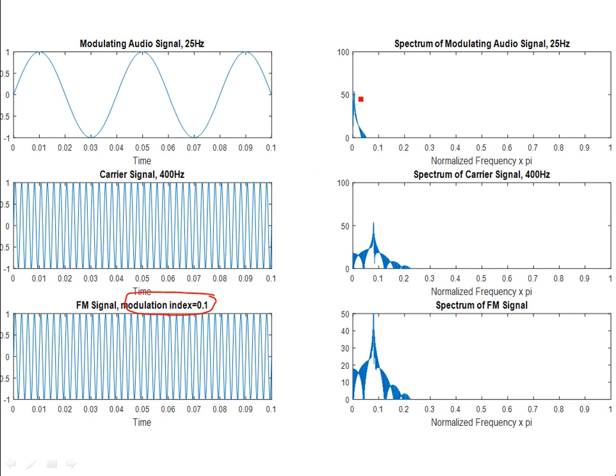So what is happening here is you see around DC, this is normalized frequency. Notice that this is normalized frequency. Normalization is with respect to fs, where normalized frequency is equal to 2 pi f over fs, where fs is the sampling frequency. But anyways, for the sake of the plot, the scale is set to the normalized frequency variable. So it has no units. Okay, so normalized frequency multiplied by pi. So this is actually pi over here. This is the digital frequency.